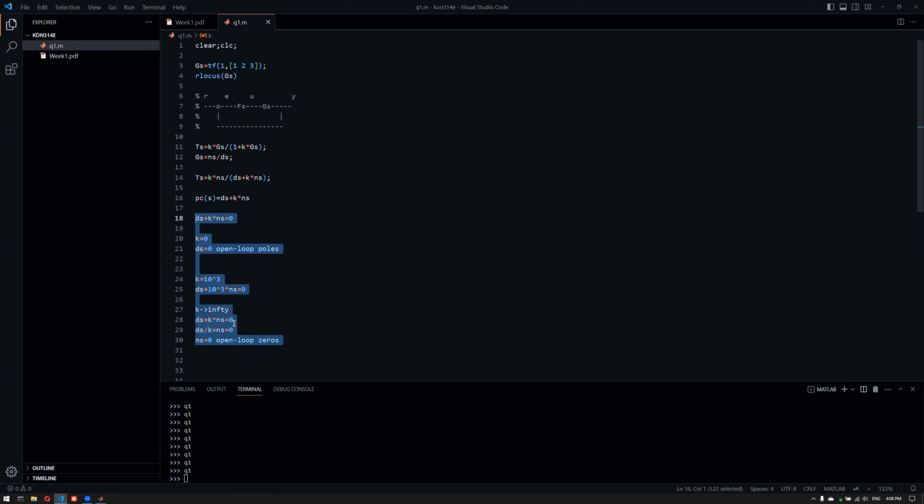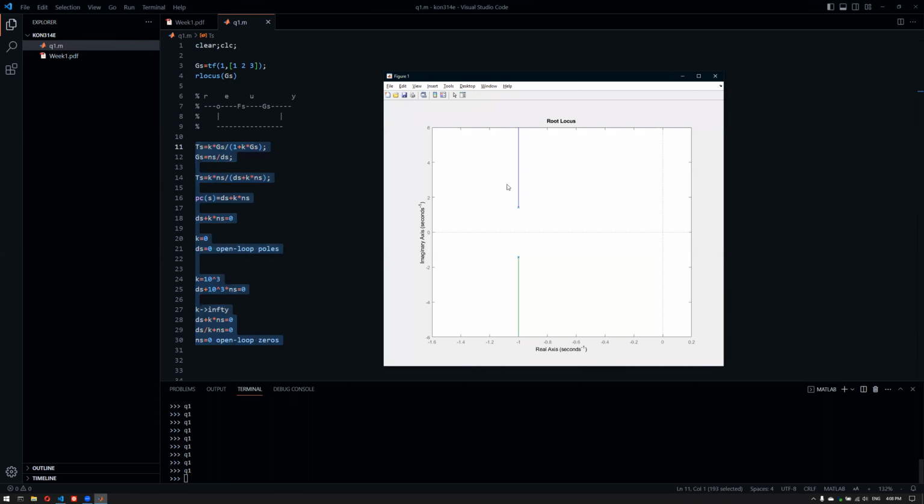So actually, Root-locus plot is basically a controller design graphic where you can choose a controller for A, stabilization of the feedback loop, because you might end up in instability, and B, for a certain design criteria, you might be looking for a controller for a certain overshoot and settling time.